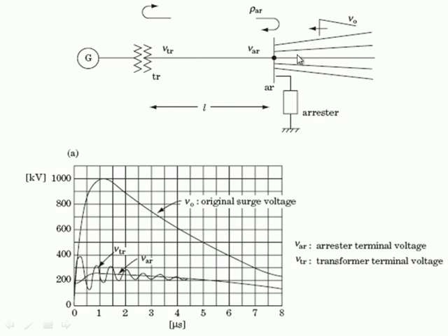Suppose we are changing the state of the system here. Suppose there is a short circuit or a load is being thrown out. So now what happens? There will be insertion of transients here. So as we have connected a lightning arrestor here, as soon as there is a rise in voltage or surge in current or voltage, this will come into play. Normally it acts as an isolator, that is lightning arrestor. Whenever there is a surge or rise in voltage or rise in current, it will activate and they will go to ground, and this will protect this system.